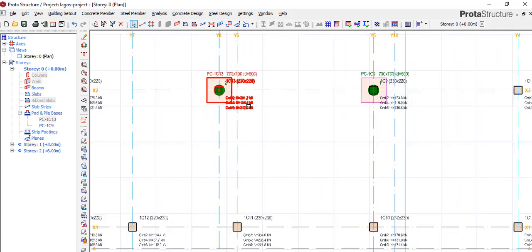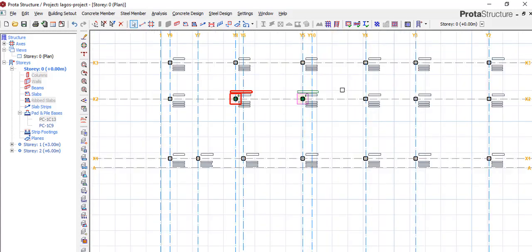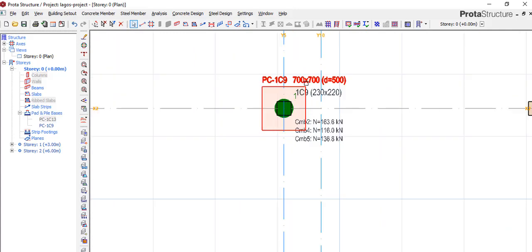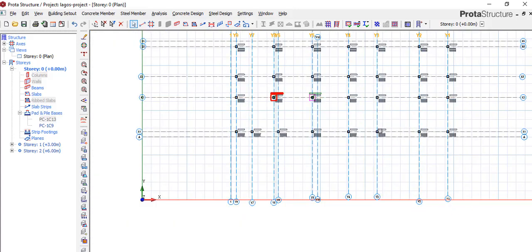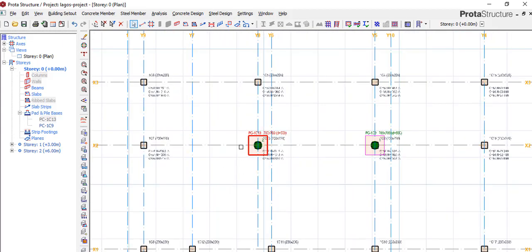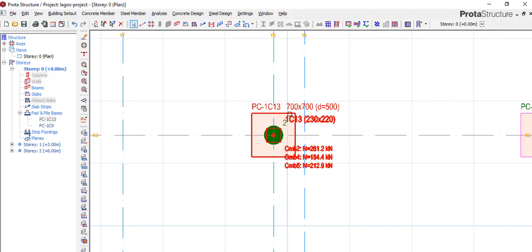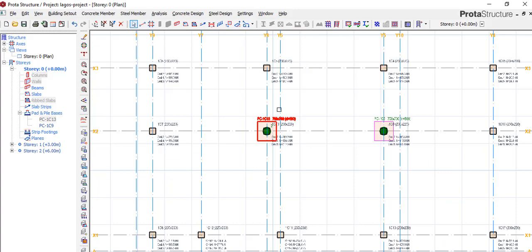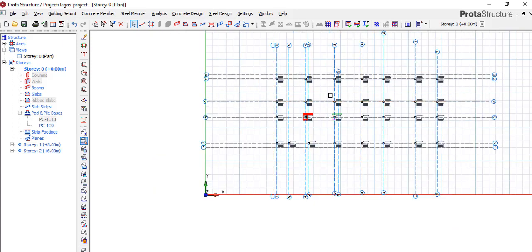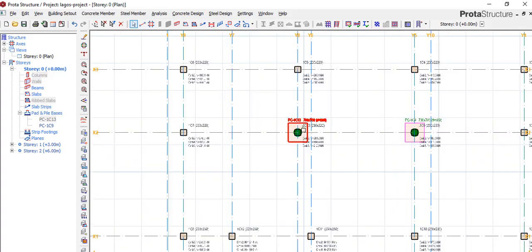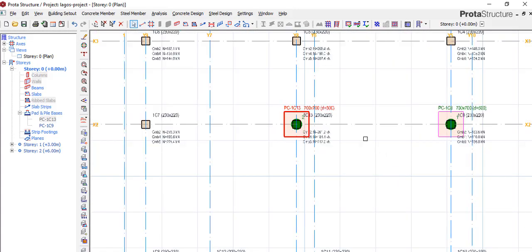So this is where you can do for all. It will be 1. Then the sample I sent to you is how you do it. After you've done all your pile cap, you connect with tie beams all around. Then you do your top slab. That is how you do for your pile design. So I hope this explains it.